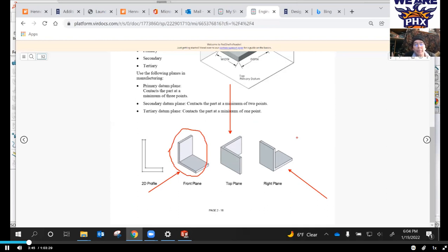I could almost guarantee you that some of the exercises that we will review at the end of the chapter where we model parts will look like this. They'll be this one, because the right plane was chosen instead of the front plane. And this is what we want it to look like.